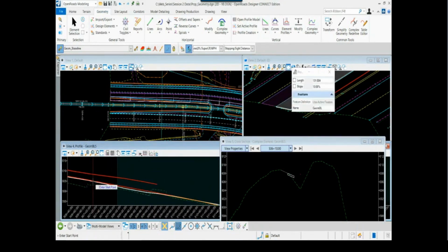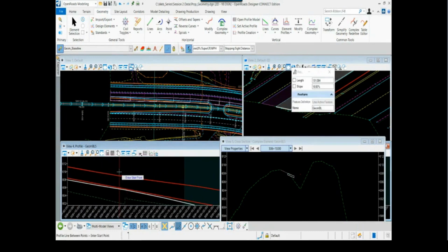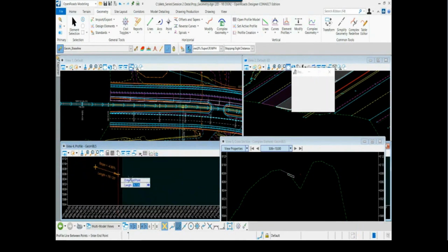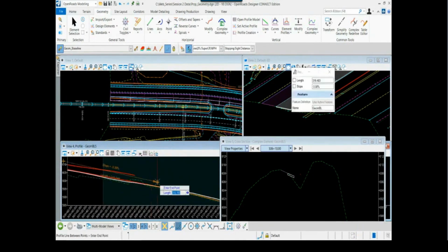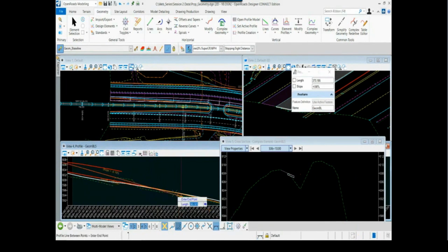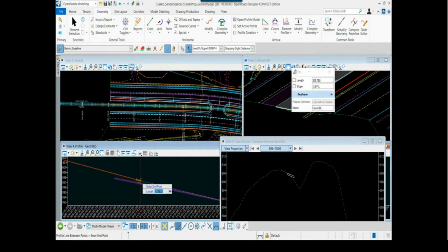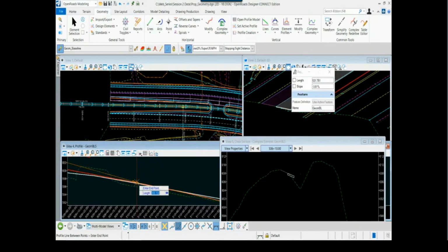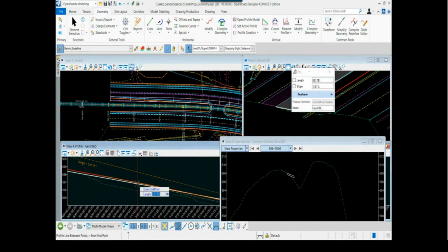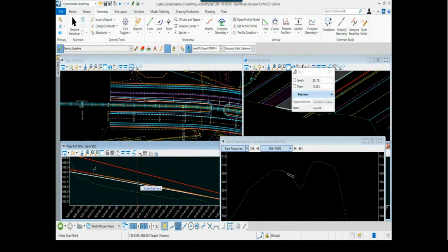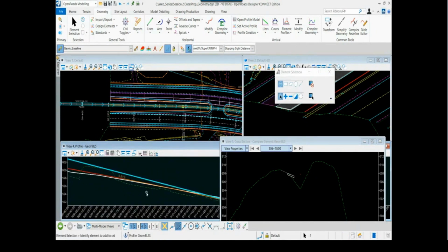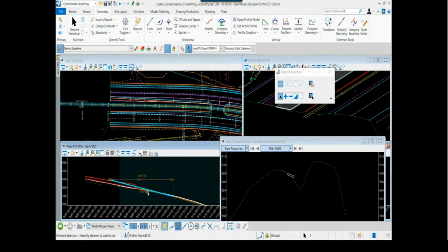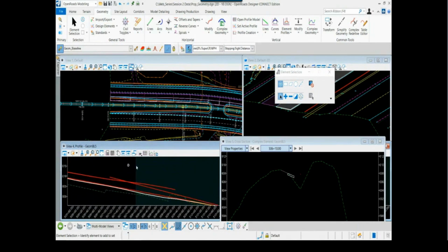I'm going to just take and draw a tangent area, again, a straight vertical line. Now I'm going to use the tangent snap in MicroStation, the MicroStation tangent snap. Let me get this view proper. And I'm going to be sure and select a tangent location to my PGL, okay? And data point. And so now I have a taper that's tangent again to that vertical curve, and I'm going to just insert another curve between my elements.